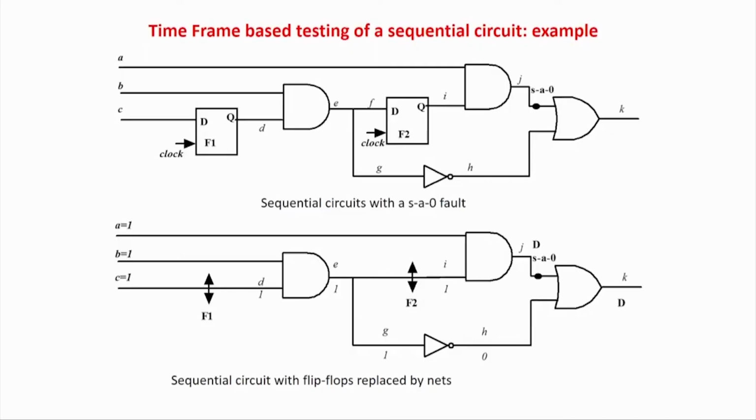So therefore, now we will try to see what we can do. Actually, just a minute, this is time frame testing. Where we are saying that without the use of a scan chain, you can still test a circuit if there are no cycles. So you have to calculate what the value will be, then check what the primary input value should be, so that the values can be propagated to the flip flops and so forth. That is sensitizing and justifying and all this. If I do that, the term is called the time frame expansion approach, because the 10,000th flip flop will be set at the 10,000th clock pulse, or the 10,000th time. But before that, all the time frames have to be set up from 0 to 9999, so that the final test pattern can be applied at the 10,000th iteration.